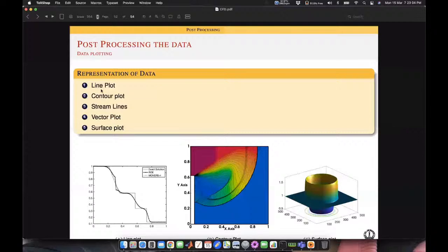But the finite element method has its own restrictions of accuracy in properly resolving shock waves and contact discontinuities. If you want conservation-preserving schemes, the governing equations that I've shown you are basically in conservative form. When you are looking at the conservative form, certain quantities are conserved. If you want to resolve this conservation, then you have to solve those equations with the finite volume method only. The finite element method may not preserve the conservation there.